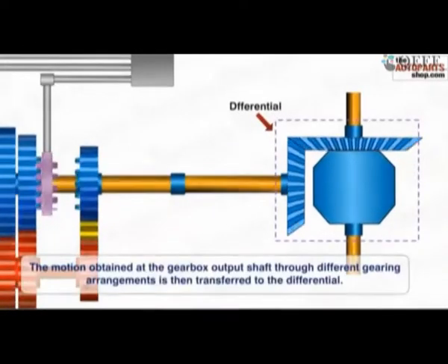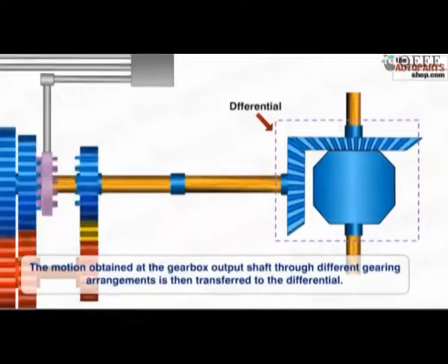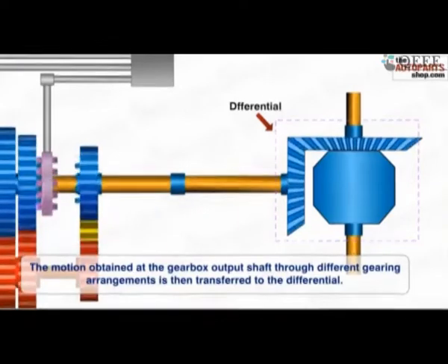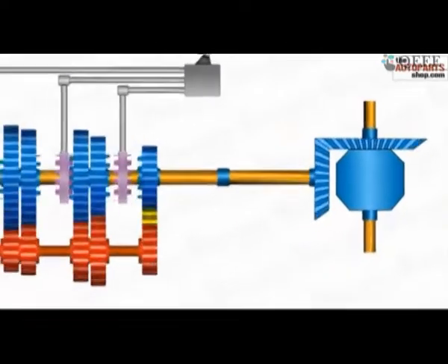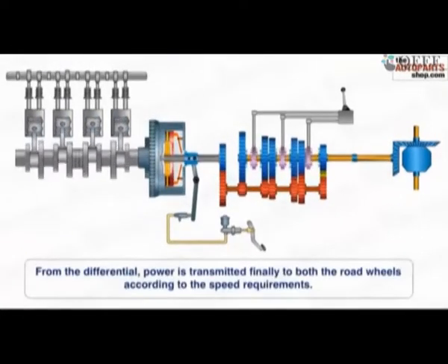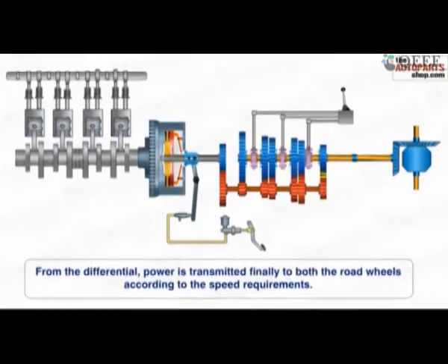This is the differential part. So these are bevel gears, and this is actually an example of a planetary bevel gear system, the differential. We will not be able to talk about the planetary bevel gear system or differential system in detail, but basically the reason why differentials are used is because you need two outputs from the same input. That's what this animation shows.